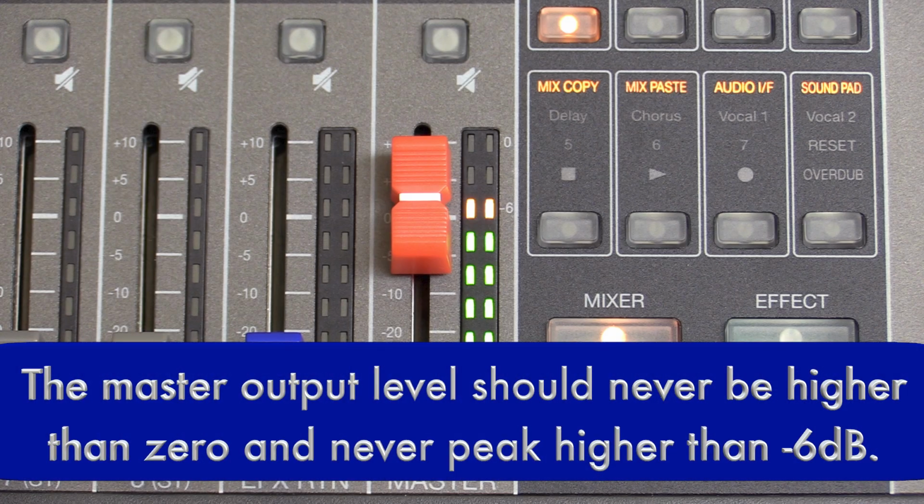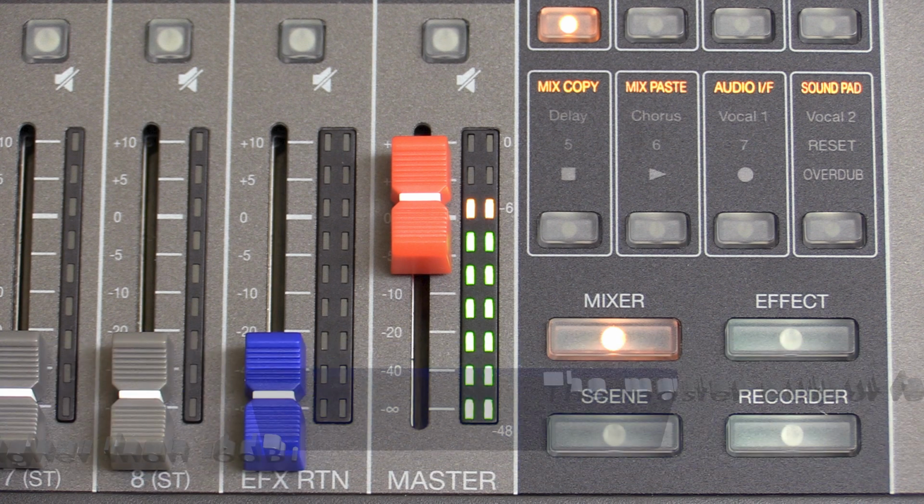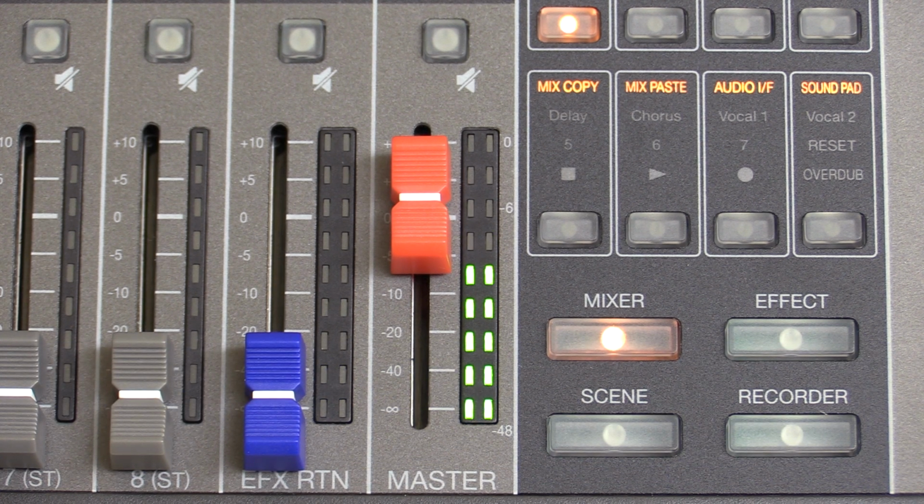Finally, we have the master output fader. This controls the final output levels of all mics used in the mixer. The fader should never be higher than 0, and the output level should only briefly peak no higher than -6 decibels.